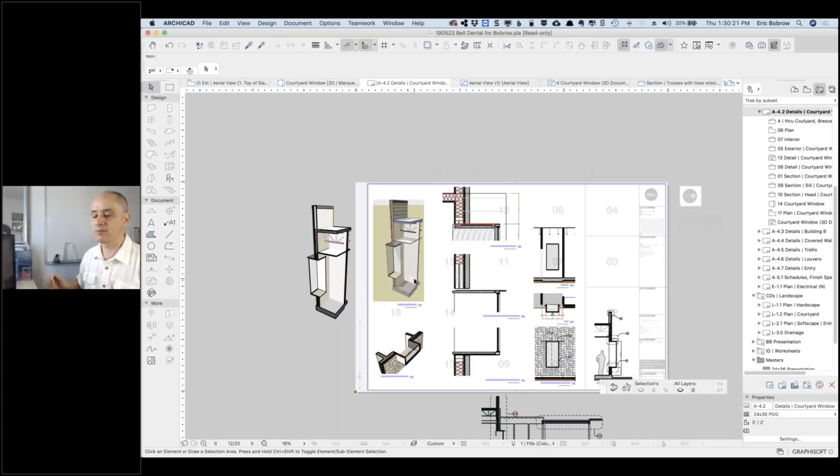Well, if you do a rendering, it's going to be essentially a JPEG or similar graphic image. You could drop it onto the sheet and then put notes directly on the sheet. Another possibility, you could bring that rendering image as just a bitmap image into a worksheet and then put notes in the worksheet, and then that worksheet view could be placed onto the sheet.